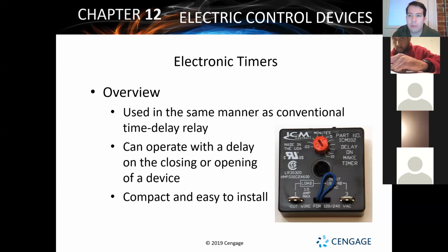One of the biggest things I would say for you to learn as a technician is to not trust yourself with how long you think 5 minutes is. You don't know how long 5 minutes is until you've waited 5 minutes. And trust me, even then, you don't know how long 5 minutes is. It's a weird amount of time to keep in your head. The trick to it is have a watch, start a stopwatch when you reset a system. Because if I turn the power off, turn the power on, that resets that 5-minute timer.